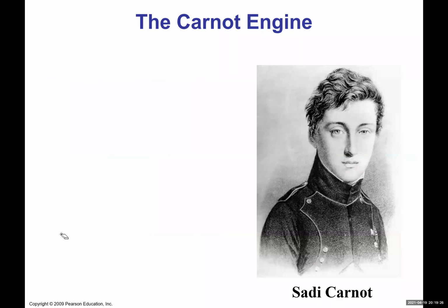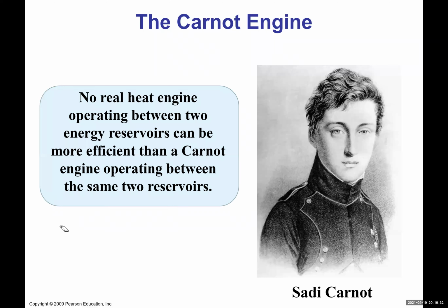And here's Sadi Carnot. He was a brilliant engineer. Unfortunately, he died very young, but he made a major contribution to this thermodynamics branch of physics. So here's what we have about the Carnot engine. No real heat engine operating between two energy reservoirs, TH and TC, can be more efficient than a Carnot engine operating between the same two reservoirs.